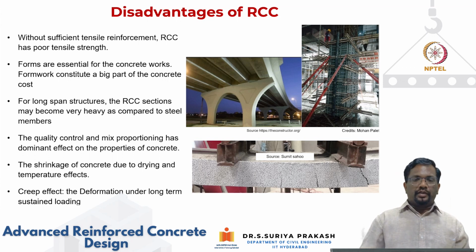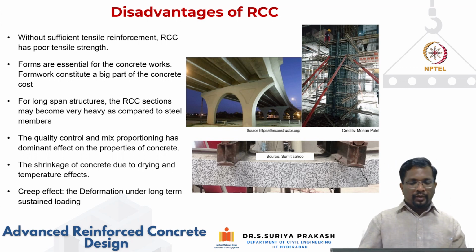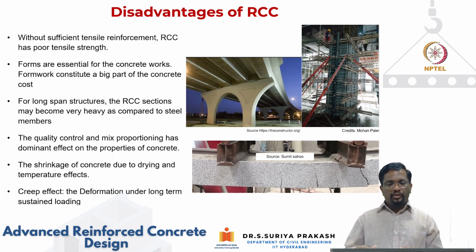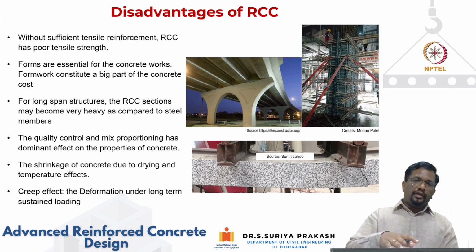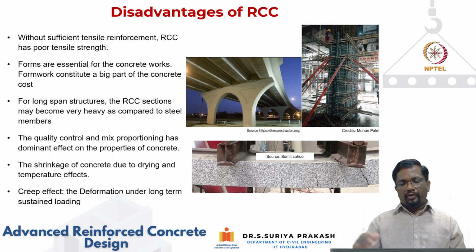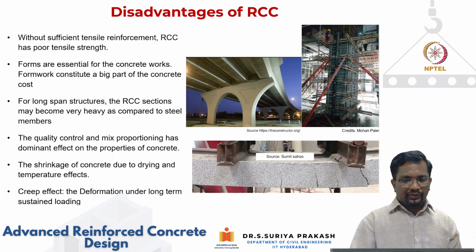Again, concrete can shrink and can lead to a lot of shrinkage cracks if it is not designed properly, right? And creep. Again, concrete also can creep. We'll talk about creep in the coming module. Basically, creep is nothing but under constant stress, the strain is going to increase over a period of time. So that will lead to additional deflections and other stresses, which we'll talk about in the next coming modules.